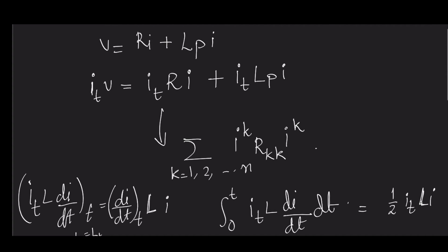Now we need to figure out the torque expression. What is the torque expression? We have to figure it out from the fact that V is equal to Ri plus PLi, where when you are talking about torque expression, you are no longer able to make it completely free like the previous case. All the time you cannot consider L constant and make it free.